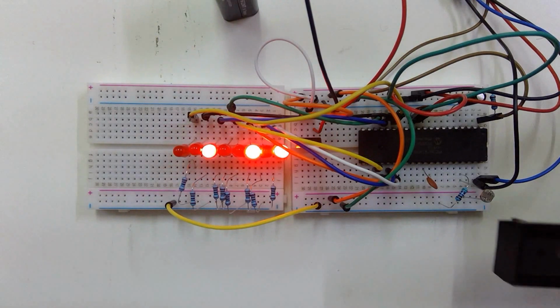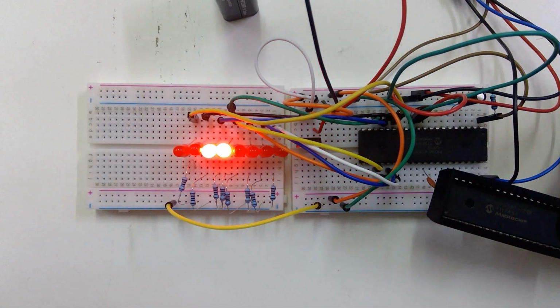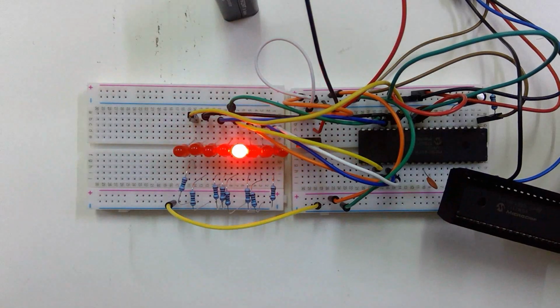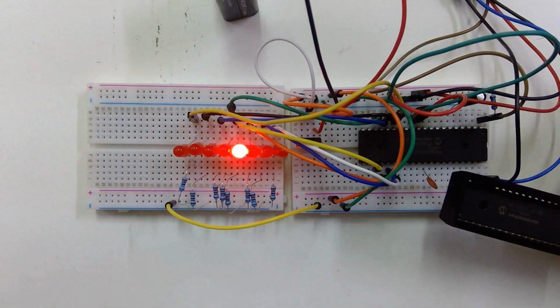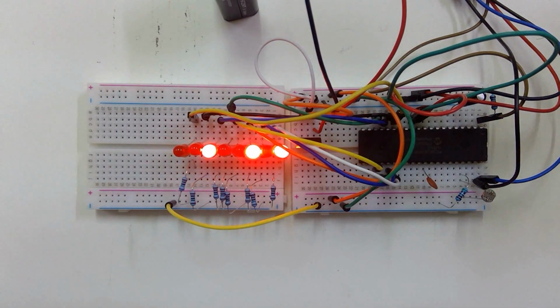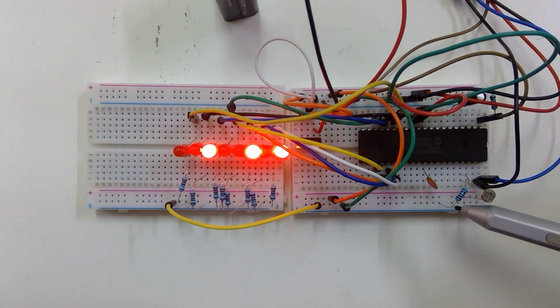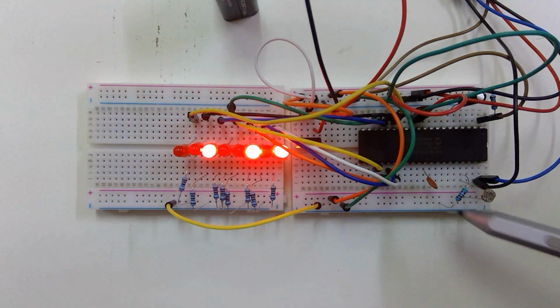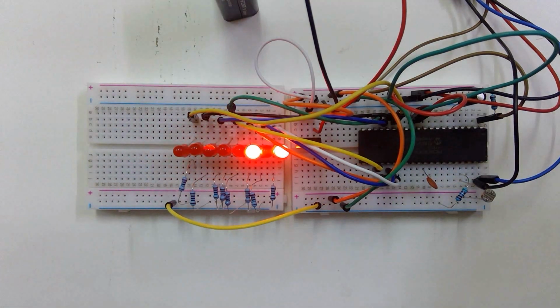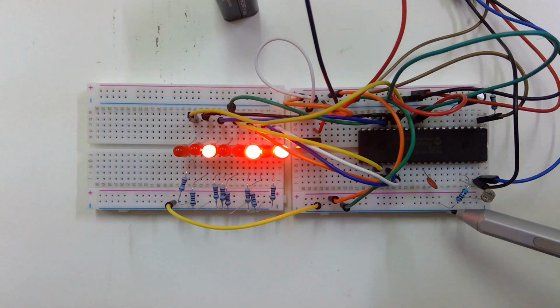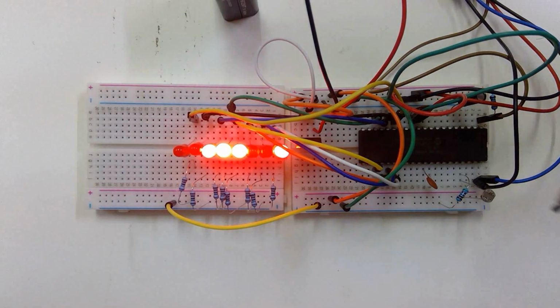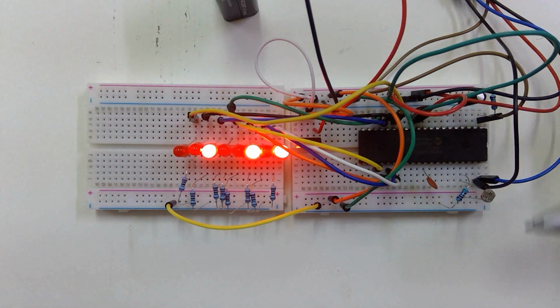Once again, let me cover this sensor here, and you can find the number has decreased a lot. And how far it decreases or how far it goes high, that depends on the resistor that you have connected here. Since this is a 5 kilo ohm resistor, you can find that the number does not decrease to 0. If you change this resistor to a very low value, then you can find the number decreases a lot more than what you see now. So as the light changes, it is measuring the light and displaying the equivalent